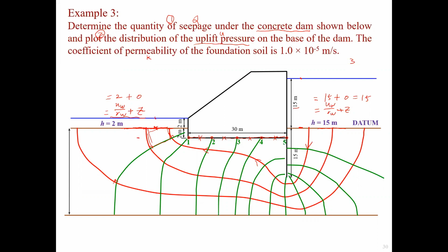That's fine as well. So to say the H value over here was 3, then over here that'll be 4 and 5 and 6? No, we don't calculate that way. Once we get the height difference and the flow length, we calculate the height difference. Delta H equals 15 minus 2, right? So it is 13. Then we count the number of head drops, ND.